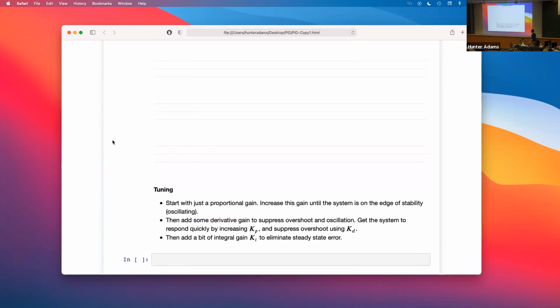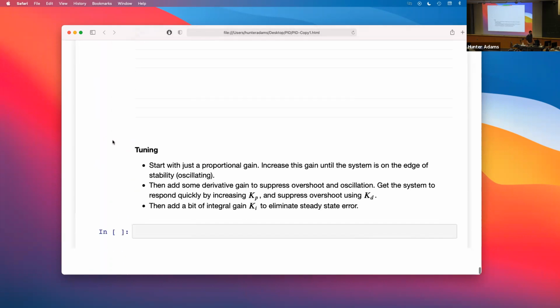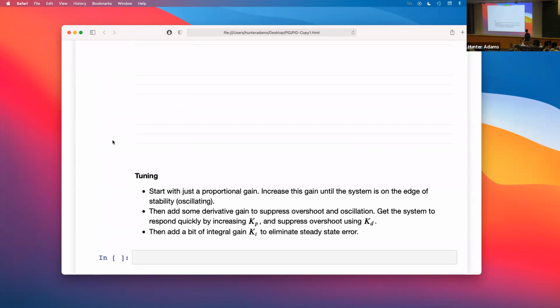So just to summarize, here's how I recommend you go about this. What is your interrupt service routine going to look like? I've said this a few times, but your code in this lab is very simple. There's a thread or 2 for taking user input, and there's a 1 kilohertz ISR. In that ISR, you're sampling the ADC. You're comparing the ADC measurement to the desired ADC measurement, and taking that difference is interpreted as the error. You then take that error, and that error goes into your PID controller.